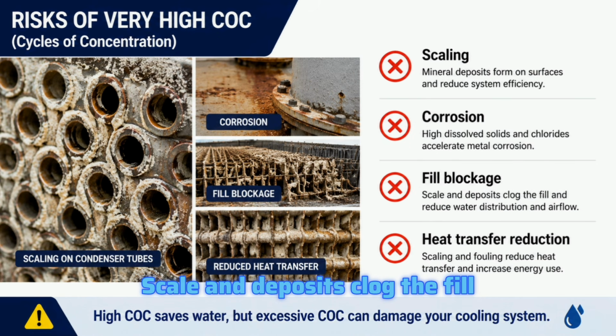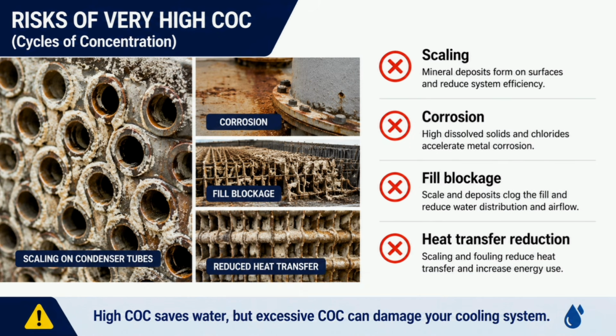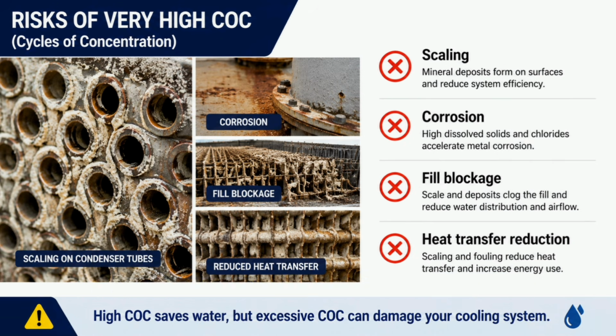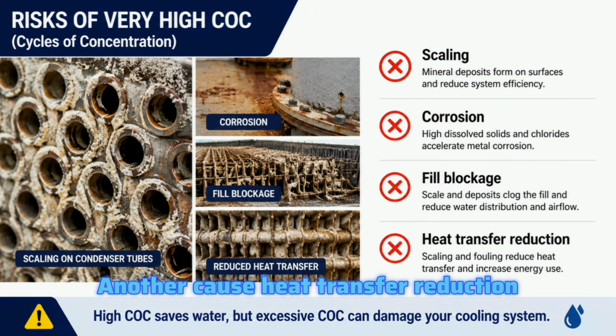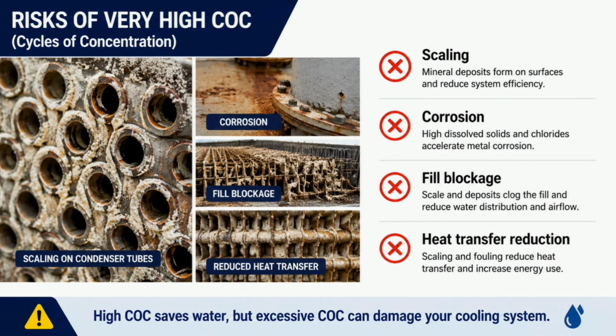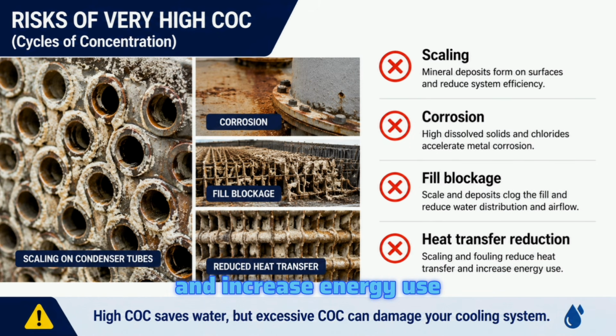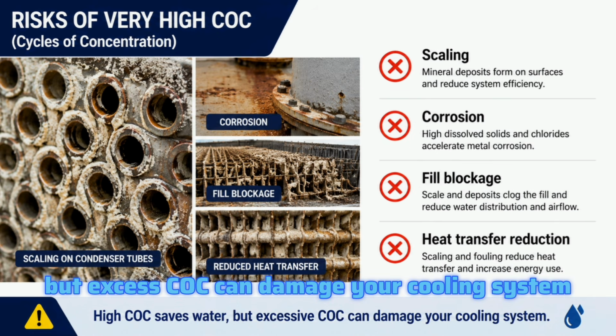Scale and deposits clog the fill and reduce water distribution and airflow. Another is heat transfer reduction. Scaling and fouling reduce heat transfer and increase energy use. High COC saves water, but excess COC can damage your cooling system.